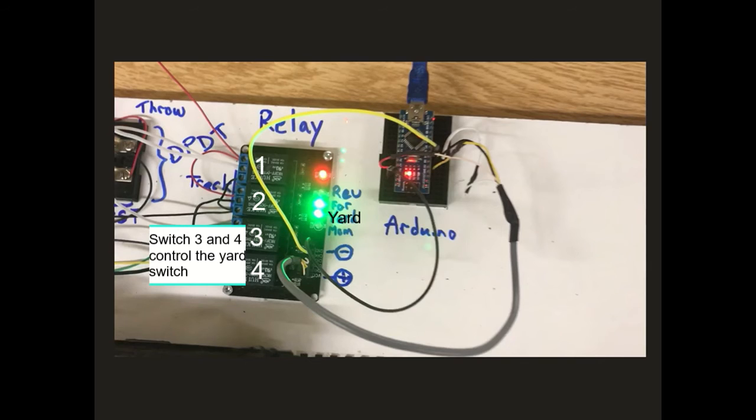One relay determines if the track will be switched toward the yard or main line. Nothing will happen to the yard switch until power is engaged with the 4th relay. The 4th relay engages power to the yard switch and is programmed to be momentary, which means that it briefly gives power for 1 second and then shuts off. This is because it is not good to send continuous power to the solenoid that is in the yard switch, or else it will burn out.